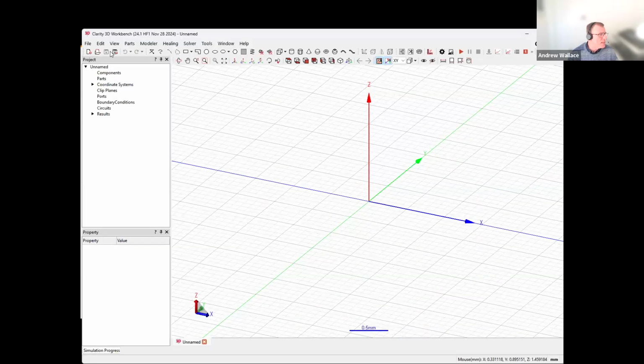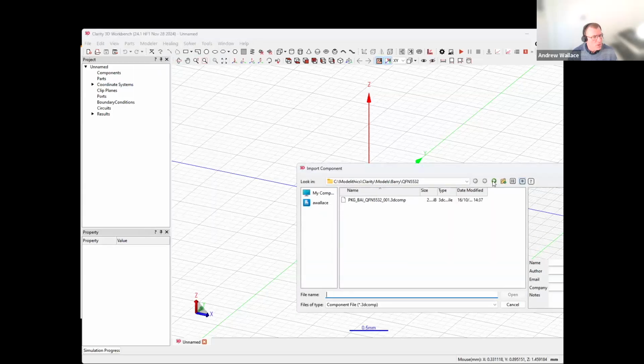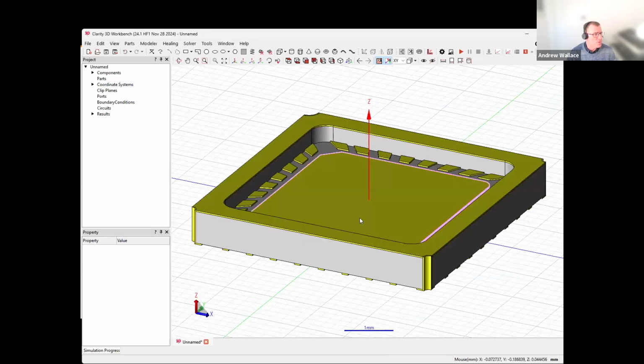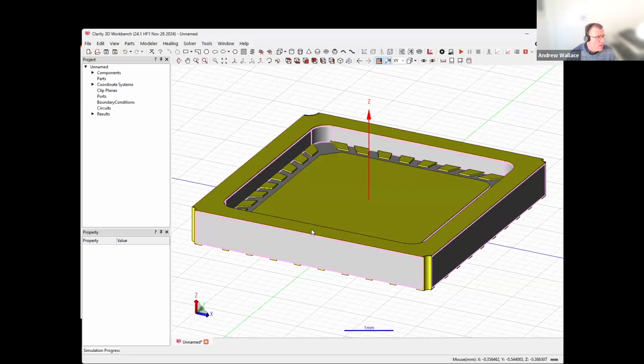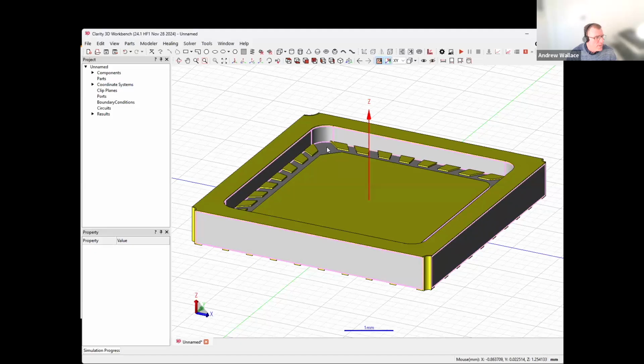And we simply start that software under the modeler, import a component, and the large list of component vendors is offered here once you install the Modelithics 3D component library. And we simply click to bring in that encrypted model as a 3D component, of which we can then have the correct dielectric material, the XYZ dimensions, the metallization, and all of the physical XYZ positions for bond wire transitions to come from a Microwave Office design out into a true 3D package.